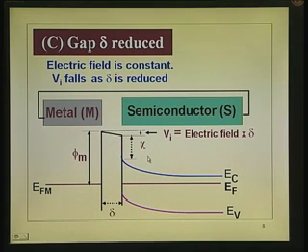That drop will be reduced, but the charge within the particular region is the same thing. The number of electrons which are moved is the same thing. Otherwise, the energy band diagram has remained the same practically. All that has happened is this drop has changed, reduced. I am keeping on reducing it, because we are talking of not MOS or MIS, we are talking of MS,